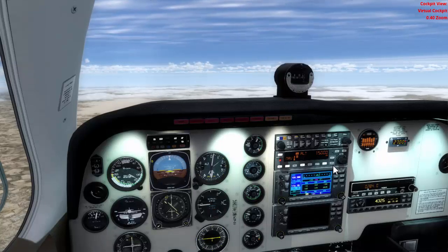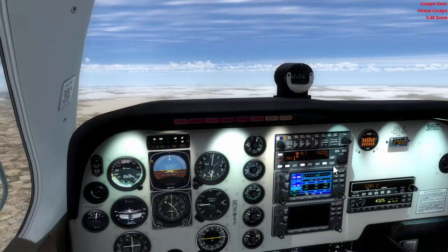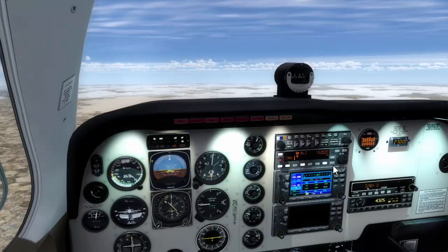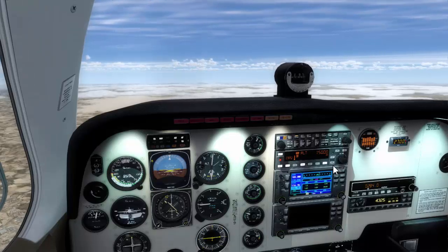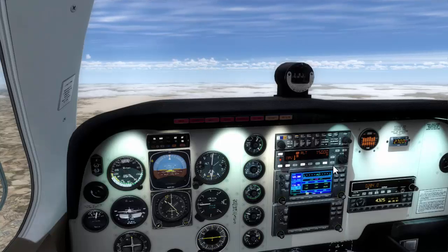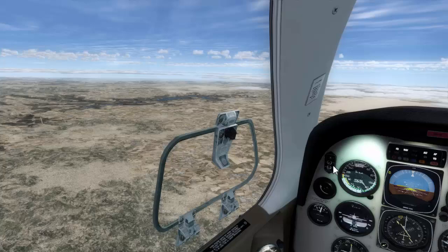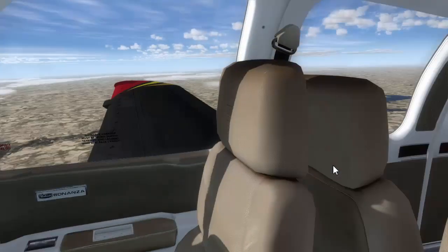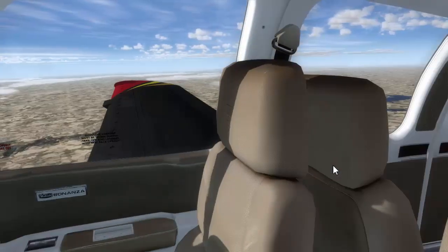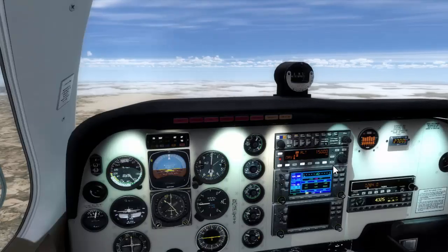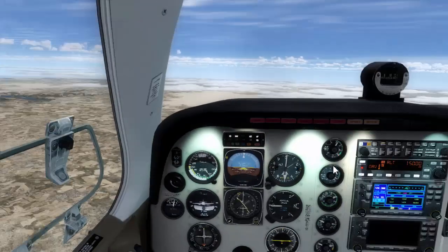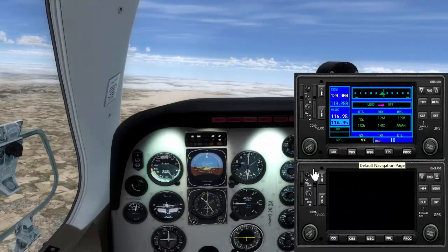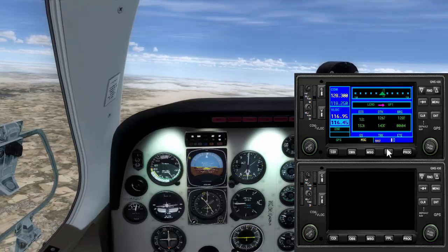In fact, you will see the sea very soon, and the approach to Ibiza is magic. I wanted to proceed with a VOR DME approach, because many people don't know how to do that, and they are asking all the time about how to proceed with a VOR DME approach. And I want you to do that also following real tables, because there are many basic concepts people don't understand about how to proceed with a VOR DME approach. And to proceed with it, you need to understand what the basic segments are to follow an approach.